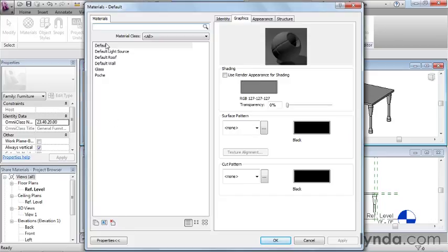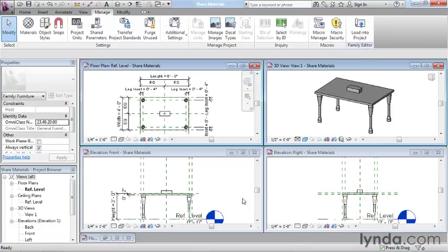What you have to do is select an existing material, one of these really simple ones that are just a plain color, and down here at the very bottom there's a Duplicate button. You'd click Duplicate, and then you'd work your way through the tabs over here to modify the material to suit your needs. It's not necessarily difficult to do that, but you run the risk of creating redundant materials because there's a pretty good chance that the material you want already exists back in the project environment.